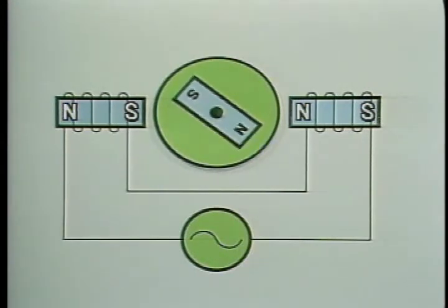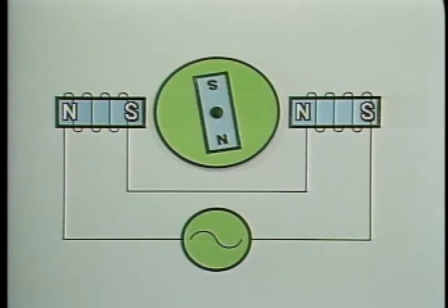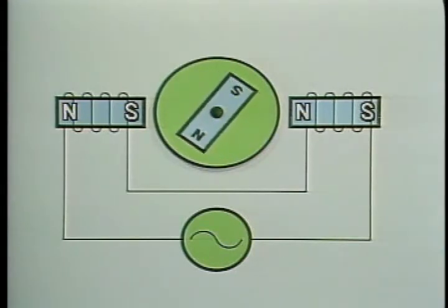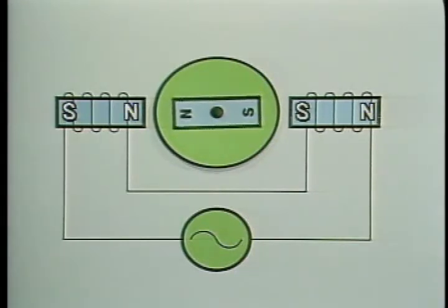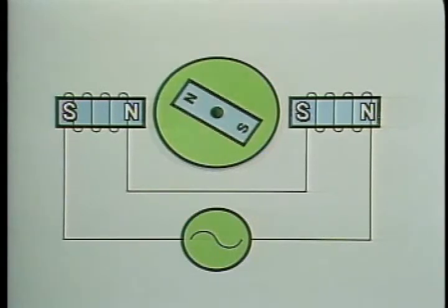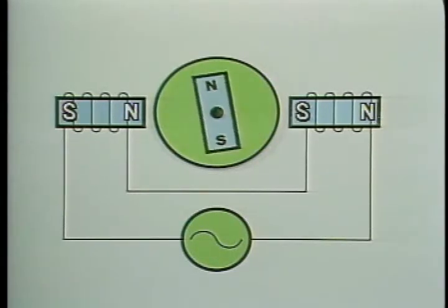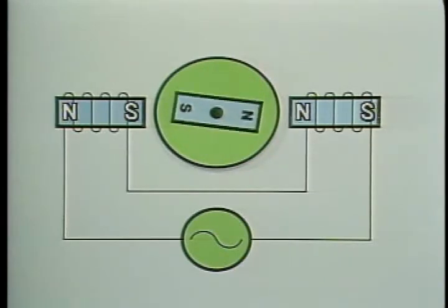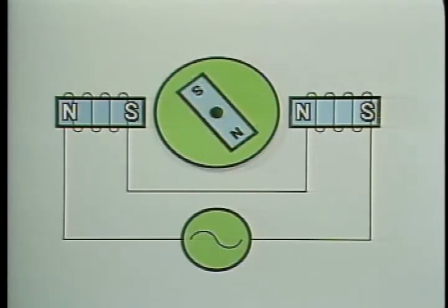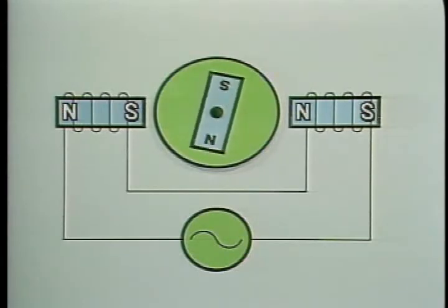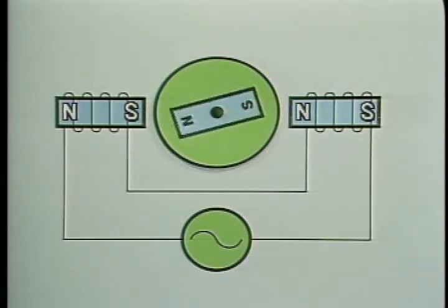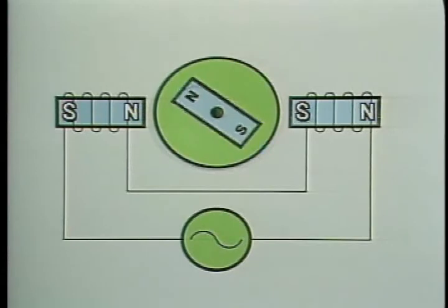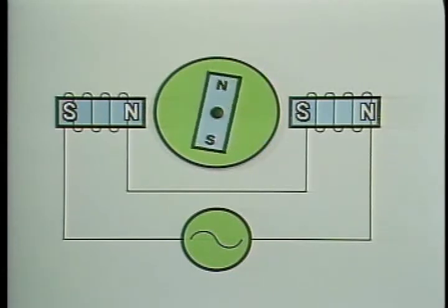The stator poles first pull the rotor poles toward them. Then the stator poles change polarity. If the rotor poles turn past the stator poles just as the stator poles change polarity, they will be pulled and pushed around, and the motor will exert torque. How fast the stator poles alternate and the rotor poles turn depends on the frequency of the alternating current.